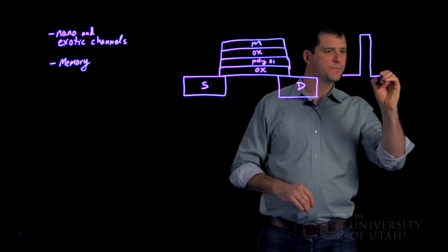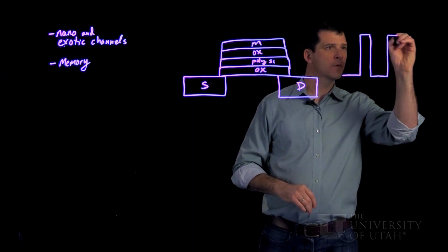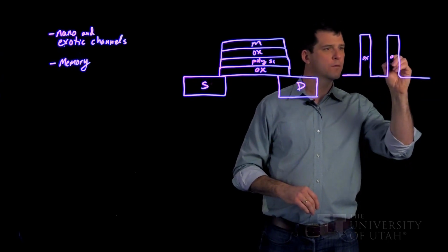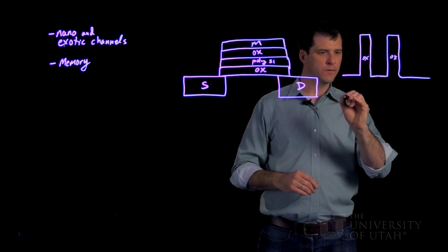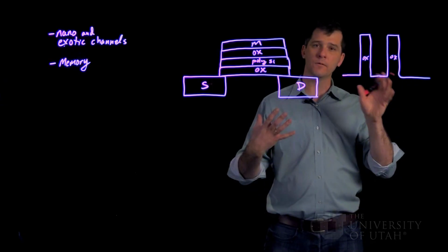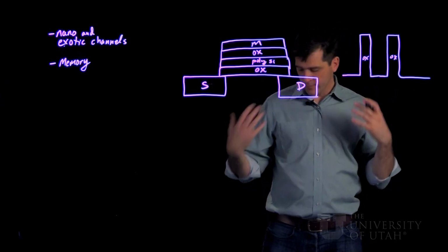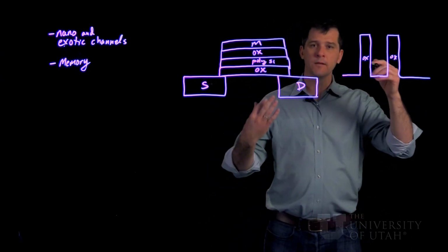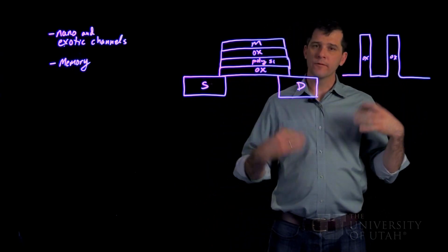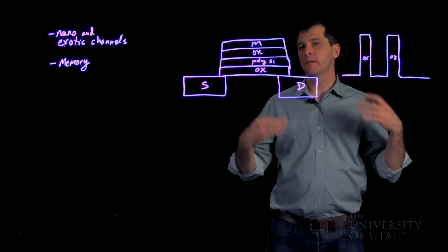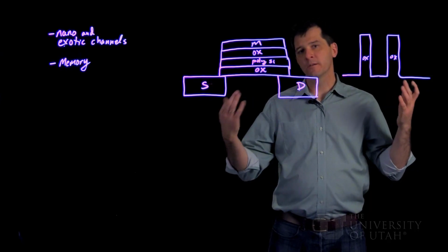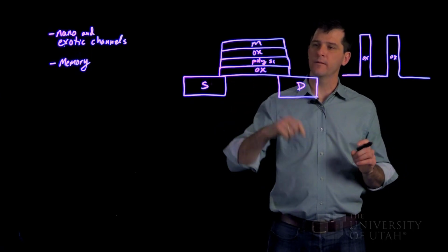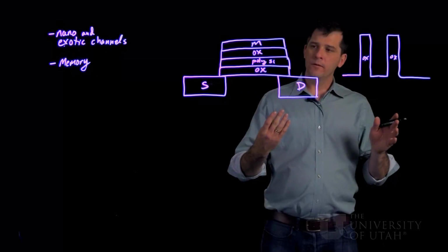we have some region here where the semiconductor is sandwiched between two layers of insulator. And this is a very large energy barrier, many electron volts. So there's virtually no chance in a billion years that the electron could leak out of this structure once it's put into this polysilicon layer. What can we do with this?